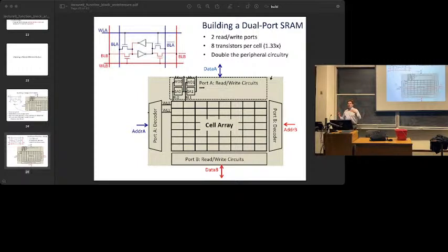If you say, I want the old data, then the timing of the signals will be changed. Quartus or Vivado will program different signal timings into the RAM block, because it's got a little bit of configurability there too. And what happens is it'll actually delay the read. The read will be done after the write is completed, and you'll actually find that your timing is worse. That's if you want to get the new data. If you say, I want to get the old data, the write will be delayed. So the RAM has the ability to delay the timings under control from the CAD system. By default, it just doesn't guarantee anything in that case, and you get the best timing. Does that make sense?